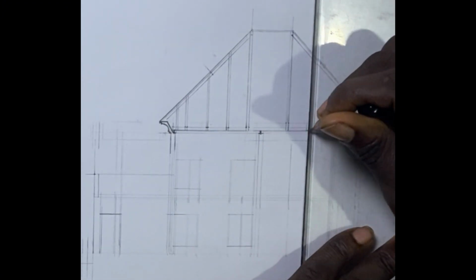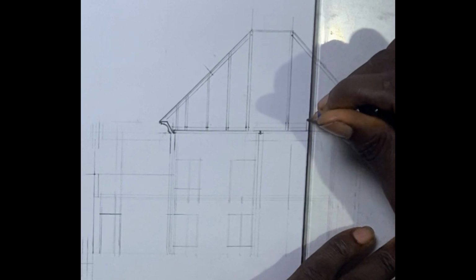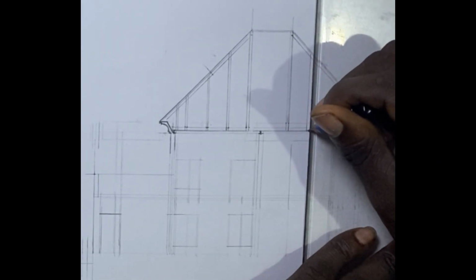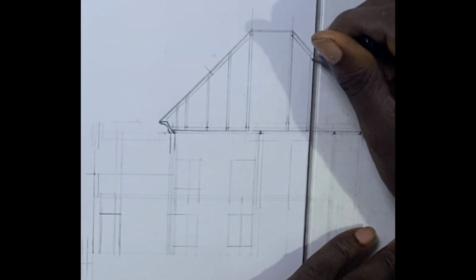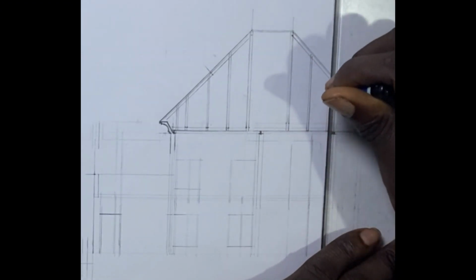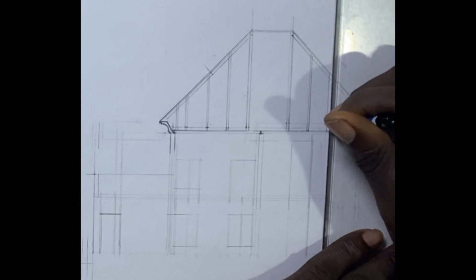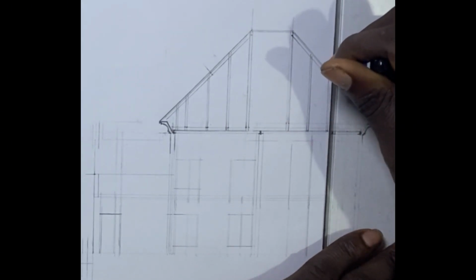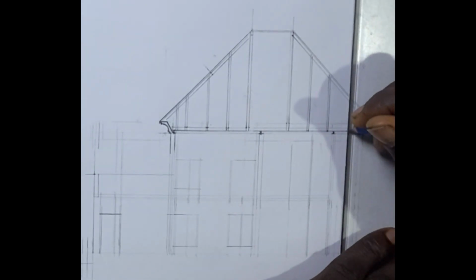All right, don't forget that your strut is 50 by 100, in which we are showing that of 100 millimeter at this side, and it is nailed to our rafter and the tie beam. You must show that it's nailed to them. That's why it's called detailing. It's not meant to be hidden. It should be visible.